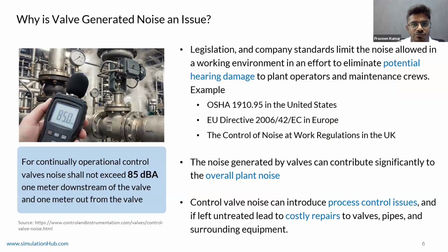We'll see those. Valve-generated noise is an issue because it contributes to potential hearing damage, so efforts are being made to eliminate it or keep it within limits. There are legislations and company standards like OSHA and the EU directive in Europe, and the Control of Noise at Work regulations in the UK. So there are different standards and guidelines.